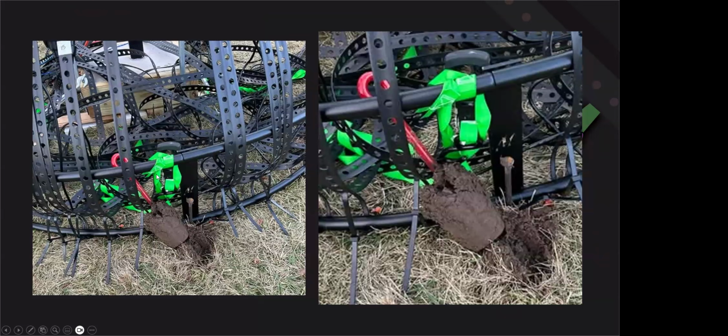Another one here. This is just a blow up of the same thing, so you can see what you're looking at. It pulls a nice cup shaped failure right out of the soil. It doesn't have much embedded in there. It does not look like it was all that deep. Deeper is always better with the anchors. The more spirals they have around here, typically the better as well. This just didn't hold up all that well.